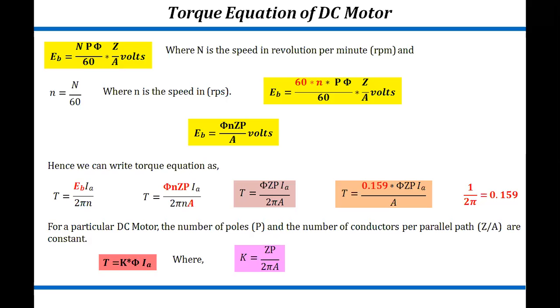Already we have seen how to increase the speed by increasing the armature current. So how can we increase the armature current? By giving the supply voltage. So here we can consider the remaining things as constant. These equations you will need.